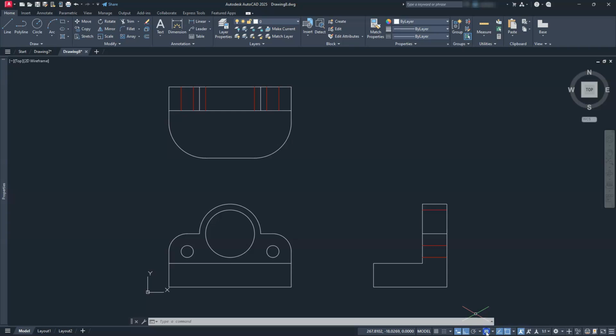So the first thing I'm going to do is get rid of my isometric. Now I'm out of isometric, and I'm ready to create a title block. Depending on which method you want to use, we can use either standard, annotation, or paper space. A lot of times when we use the 3D stuff, that's paper space, so I don't want to rehash that again. I like to eventually go between either annotation or the standard. In this case, I'm going to use the annotation one.